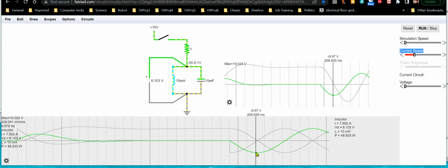But at any rate, right when you flip this switch, we go from it generating 10 amps, just sitting there happy, it'll stay there forever, to all of a sudden, when I flip the switch, the current through the capacitor jumps to maximum, as you would expect a capacitor to do when you're first applying a voltage across it. And you can see what the voltage being applied to the capacitor is. It's coming from the inductor, from the current.